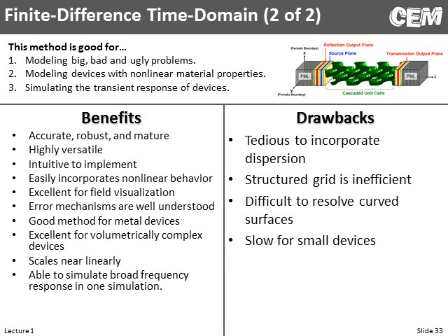But also being a time domain method, it's better for nonlinear devices. It's better for very broadband simulations, but horrible for really resonant things. And one of the assignments I give in the finite difference time domain class is I give you something very resonant to simulate, and you watch the wave hit it, it gets stuck in the thing, and it just bounces. And literally, your program will be running for hours until this energy finally leaves, either as transmitted or reflected energy. So that's a real drawback of a time domain method.